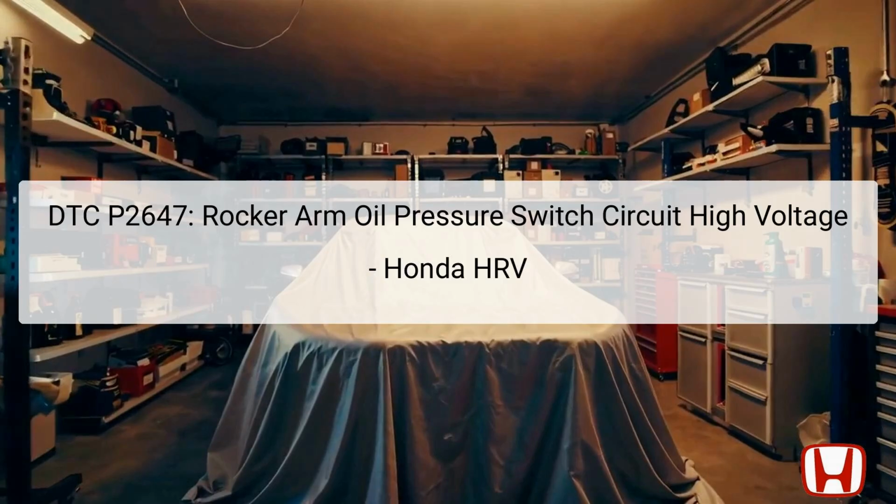In the Honda HRV, the rocker arm oil pressure switch is usually located near the rocker arm oil control valve. If this sensor detects a voltage that exceeds the predetermined threshold, it triggers the DTC P2647. When diagnosing this issue, having specific special tools for pressure testing is essential to accurately assess and resolve the problem.